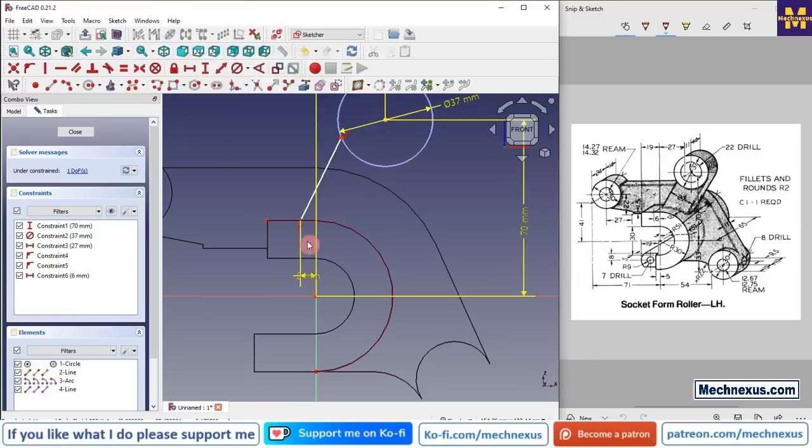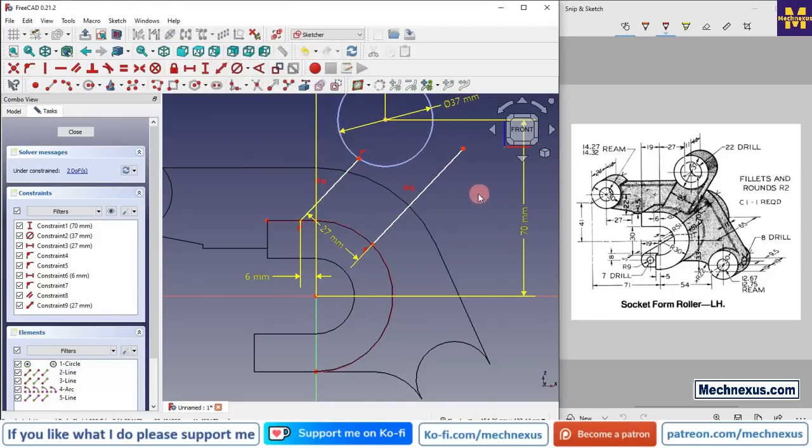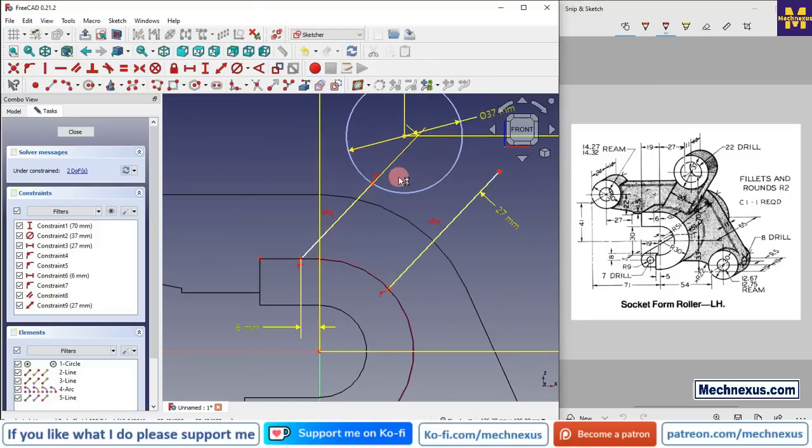And now we will select the line tool and create an angular line, and select this point and add a horizontal dimension of 6 mm, and we will select one more line and we will add the parallel relation, and here we will select this point and this line and add a dimension of 27, and here we will select this and add a tangent relation, because this is the tangent.